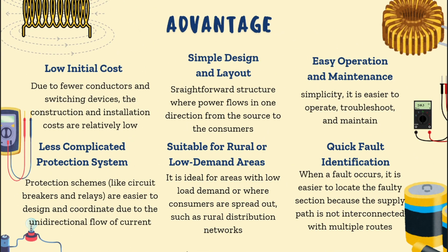For the advantages, firstly is low initial cost due to fewer conductors and switching devices. The construction and installation costs are relatively low. Next, simple design and layout, a straightforward structure where power flows in one direction from the source to the consumers. Thirdly, easy operation and maintenance. Because of its simplicity, it is easier to operate, troubleshoot and maintain.